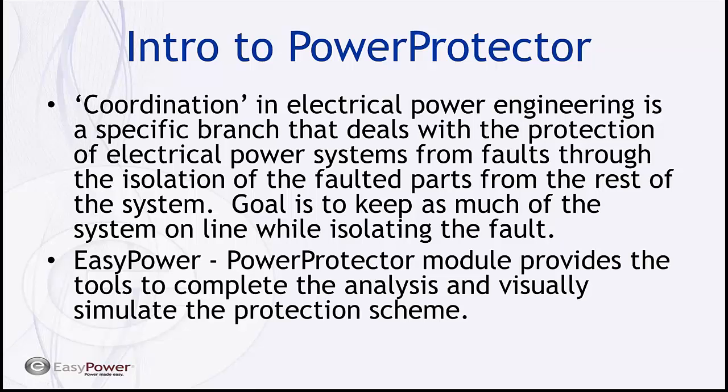Okay, so coordination in electrical power engineering is actually a specific branch that deals with the protection of electrical power systems from faults through the isolation of the faulted parts from the rest of the system. So the goal is to keep as much of the system online while isolating the fault and preventing any additional damage due to the initial incident or fault. In EasyPower, the module that we utilize to simulate and analyze this is called PowerProtector, and it provides the tools to complete the analysis and visually simulate the protection scheme.